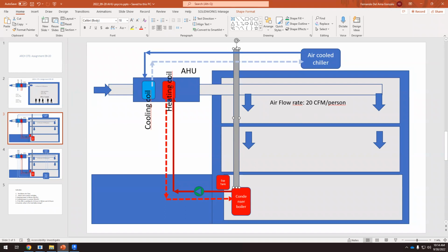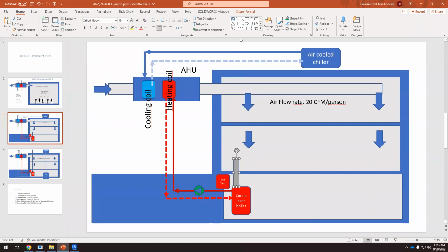For example, students always ask, can we get rid of the exhaust air through a window? No, we can't. This is forbidden. Why? Because people walking on the street would be forced to breathe the exhaust gas, this poisonous gas that comes from the boiler. This can't happen. You can't have these kinds of gases in contact with human beings, so don't do this.